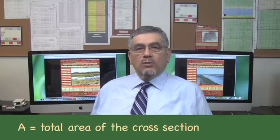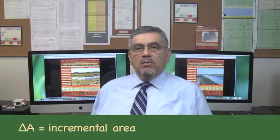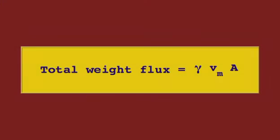Assume A equal total area of the cross-section, V sub m equal mean velocity of the cross-section, delta A equal incremental area, V equal velocity through the incremental area. The total volumetric flux or discharge is Q. The total weight flux is gamma Q, in which gamma is the unit weight of water. The incremental weight flux is gamma V delta A.